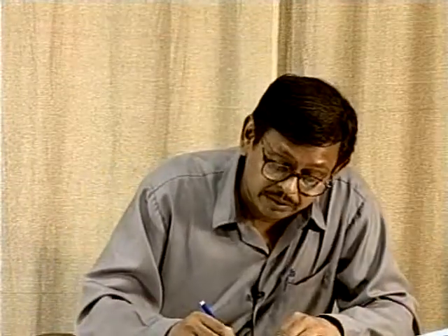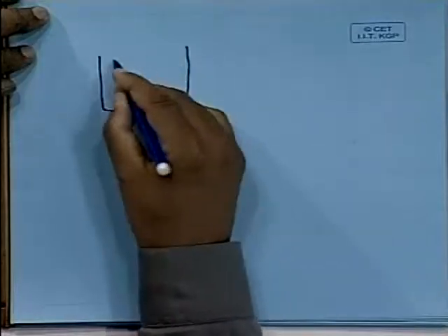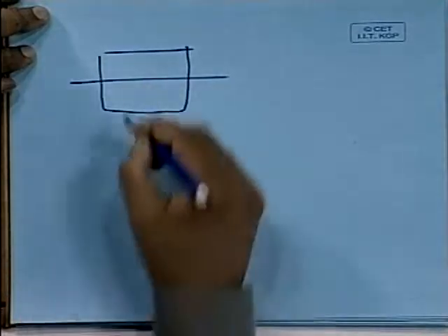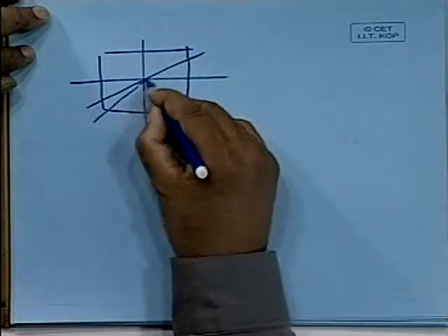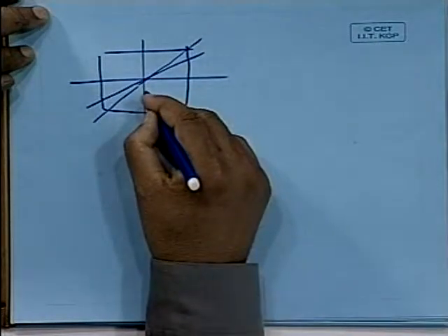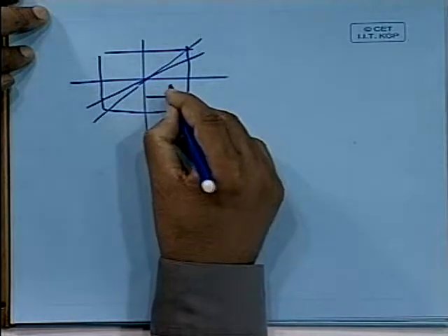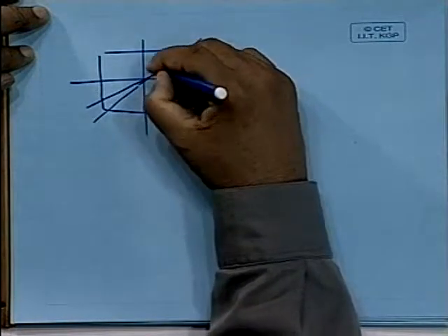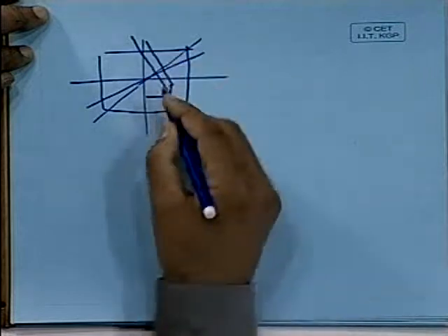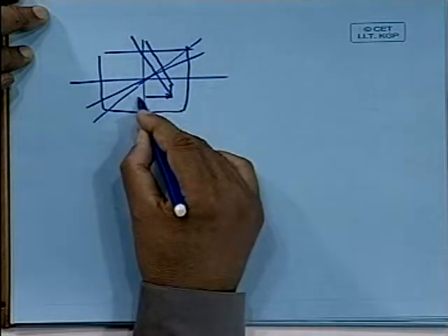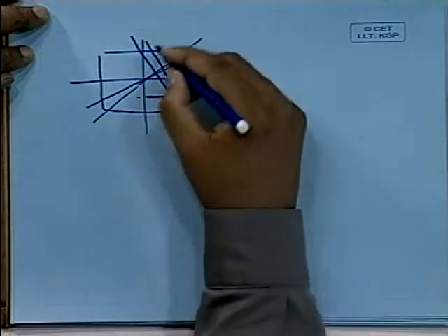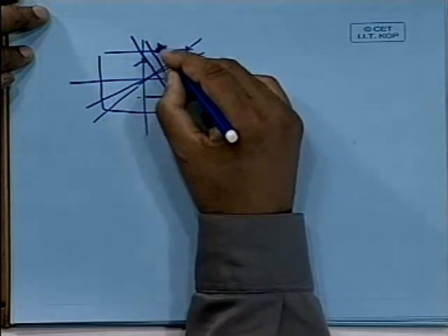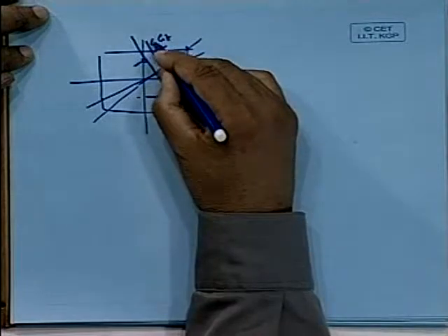Now you take a ship like that, just a wall sided shape. Now we have seen for a wall sided shape, what happens is that as the angle goes large, basically B goes here as well as B goes up here. Essentially, the center of buoyancy not only moves to the side, it also moves up. This upward movement gives an additional delta GZ type.